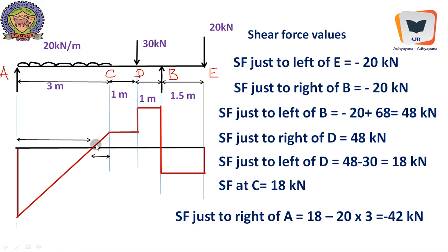And here we get an important point once again, where shear force crosses its sign. There is no nomenclature associated with this zero shear force point, but anyway it is to be located. Because wherever shear force is zero, we will prove later that the bending moment is going to be maximum. Therefore, we need to locate this particular point.